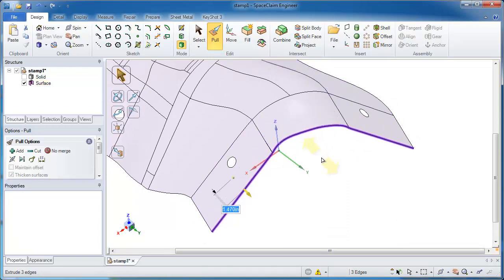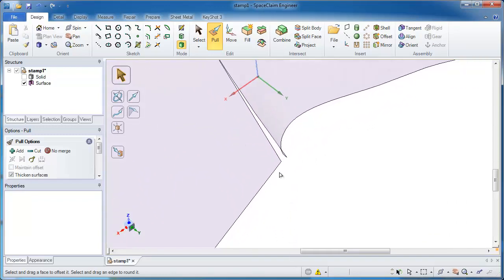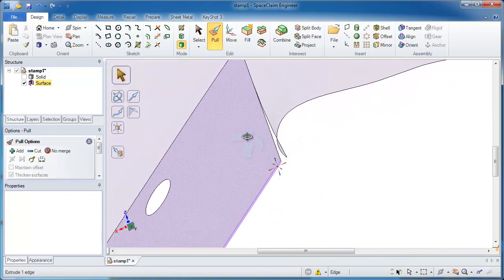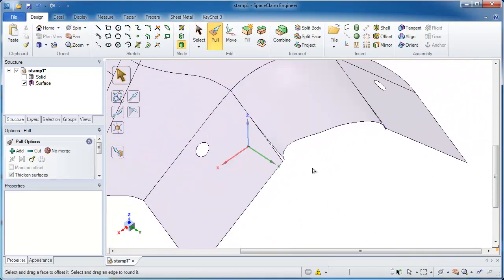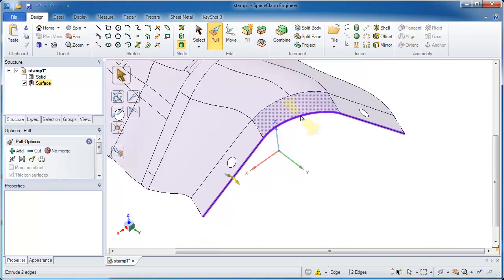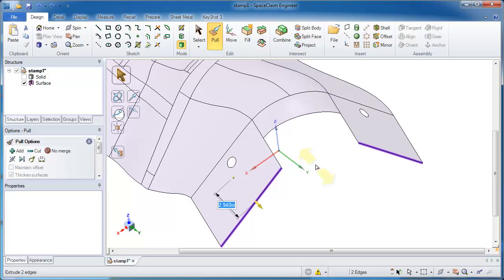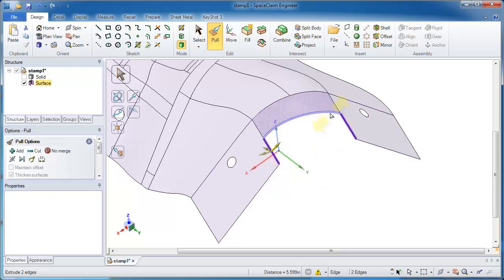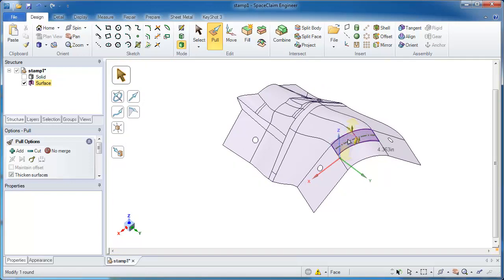When I drag these three edges together, not only do they extend at different lengths, but the curvature of the surfaces does not lend itself well to preserving the continuity between the surfaces. So that's a good reason why I need to extend these out at different rates, or at different times, if you will. I'll extend maybe just two of them out for the time being, and then just as before, as I've been doing all along, loft between a couple of edges. And I get a contour that is good enough for creating the necessary runoff.